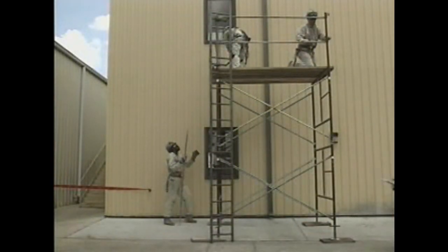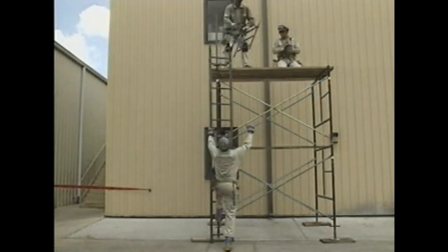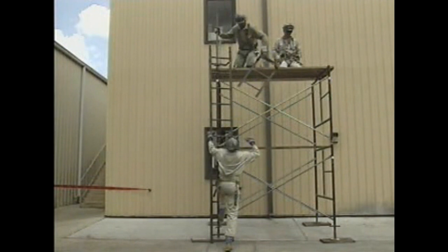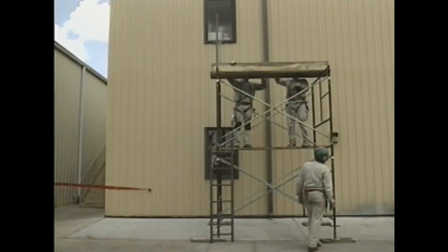Then the upper and middle guardrails are removed, along with the guardrail posts. The upper sections of the ladder are then disconnected, and the scaffold flooring is removed.